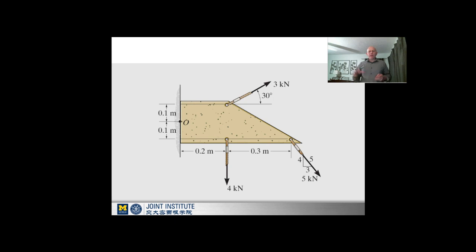Now, when we apply these forces, if we wanted to calculate the moment at O, where we're attached to the wall, one of the reasons we might want to do that is to see if the bracket could be fractured or broken from the wall, which you'd learn about a bit later on in the semester. But we would want to know what is that force on the wall, applied at the wall from all of these tension members. So the way of doing that would be the summation of R cross F.